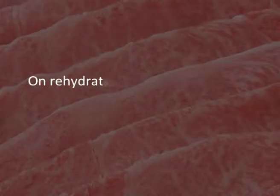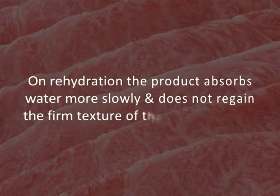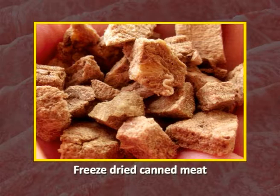Mechanical drying involves the passage of hot air with controlled humidity. When hot air is blown over a wet food, water vapor diffuses through a boundary film of air surrounding the food and is carried away by the moving air. On rehydration, the product absorbs water more slowly and does not regain the firm texture of the fresh material. In contrast, there are better reconstitution properties, nutritive value, and acceptability in the case of freeze-dried meat.